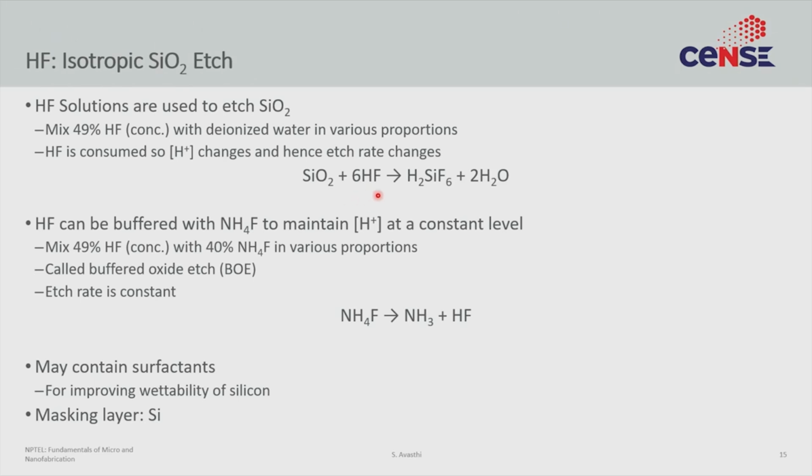And this is a trick that we do in wet etching all the time. We are doing microfabrication, so the films that we are etching are only a few nanometers. And even if you are etching it on full wafers, I urge you to do the math, you are trying to remove somewhere between micrograms to nanograms of material per minute. And at that low material removal, you do not need a lot of chemical. Again, if you do the math, it probably only requires a few ml of actual chemical to do the etching.